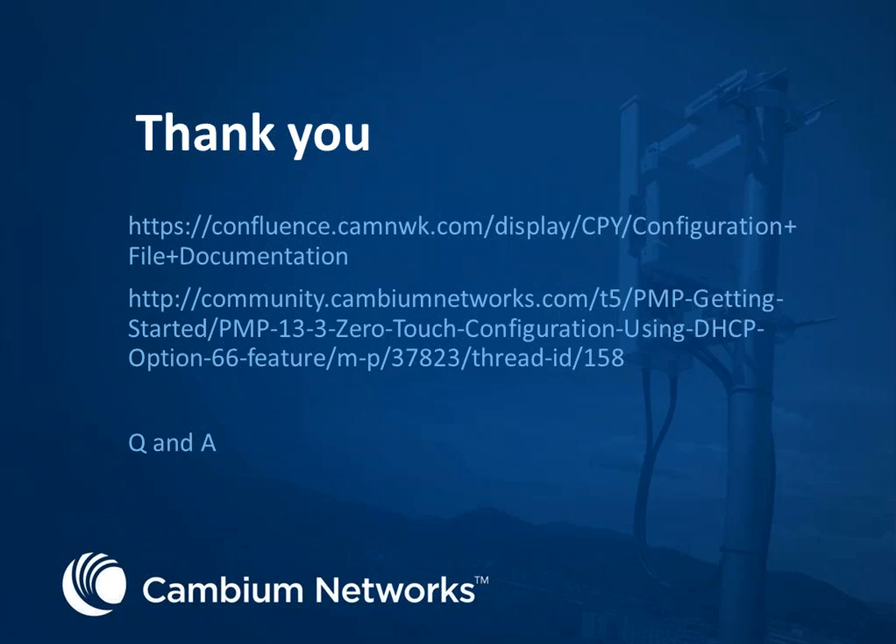But right now, this whole zero-touch configuration is doable without CN Maestro, so you don't need any additional software. Until we are supported officially as PMP450 in Maestro, this is how you do it. Once Maestro comes online in Q1, we'll be able to do it through Maestro as well.